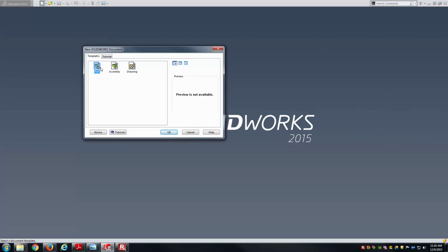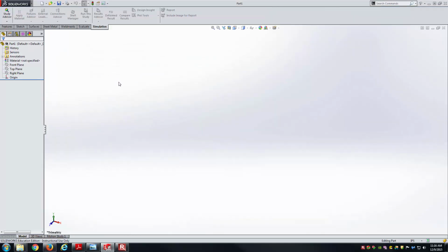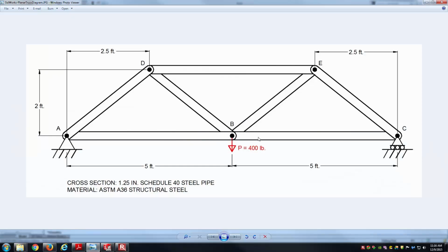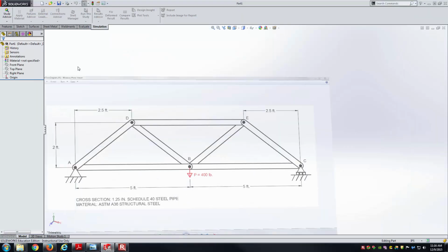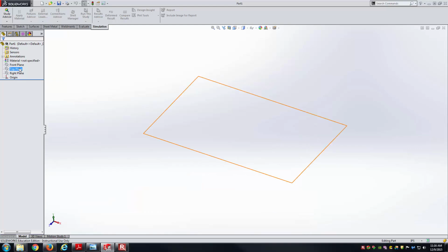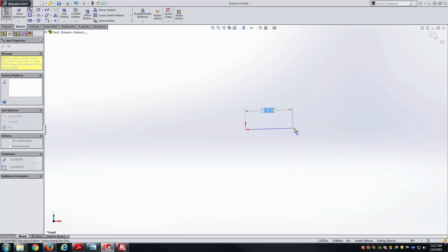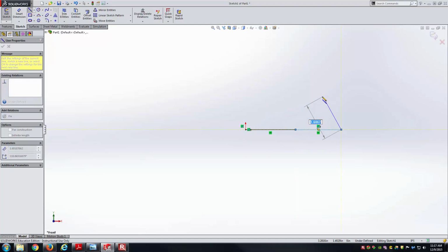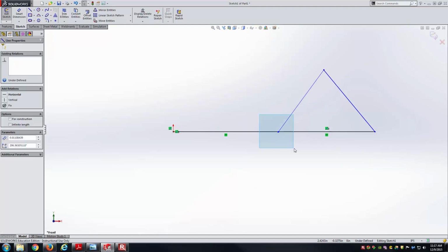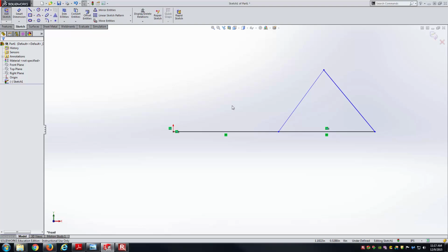The first thing we're going to do is use weldments in order to draw the truss geometry. If you haven't used weldments before, what we're going to do is make this sketch using just the lines inside of the sketch environment here. I'll get on the front plane. Oop, a little bit of lag there. Now I've made it to the front plane, and here I'm just going to very quickly make a rough sketch of this model. I've got a little baby line there that I accidentally generated.